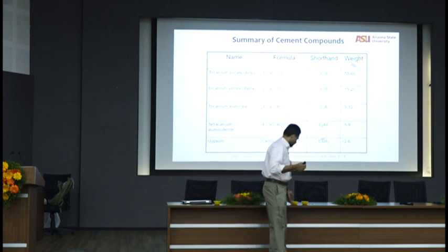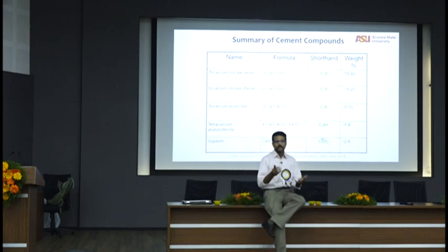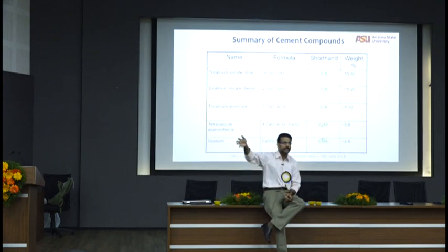Here also, generally, you can make different grades of cement in two different ways. The first way is you can change the amount of C3S that forms by changing the chemical composition of what goes inside the kiln. So that you get a 53 or a 63 grade cement if you have a large amount of C3S that's forming, right? So you can change your raw material ingredients. I don't know if that is done in India? In some plants they do.